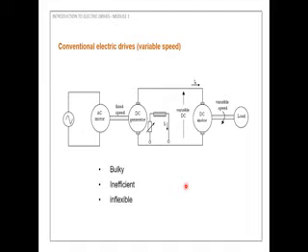Initially AC voltage is given to the motor, which starts rotating and is coupled with the generator. When the motor rotates, the DC generator starts rotating, and DC voltage is generated and given to the DC motor. This arrangement is coupled with the load.